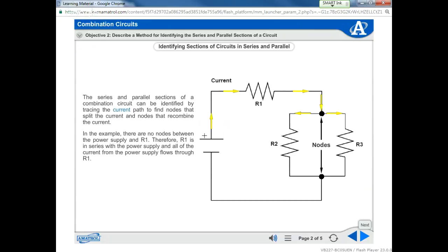All right. Okay, so here we have a combination circuit, and notice our current. Our current in this portion here is in series. Okay, and it comes over here, and then we split just like a parallel circuit. So what's constant in a series circuit? Current. So at this point, whatever's coming through here is going to be IT. That's the total current, okay? Because that's coming through here. And at this point, it's still going to be IT, right?